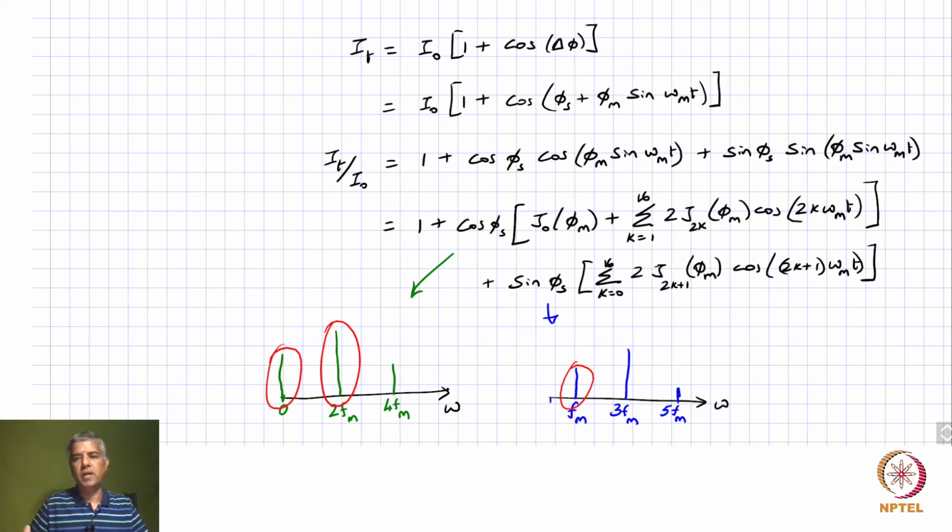So, all the advantages of a phase generated carrier in terms of noise suppression, because you are interested in only this component, you can essentially just beat it with those frequencies and put a low pass filter, so you can reduce the external noise, whatever external perturbations there are, to a large extent.